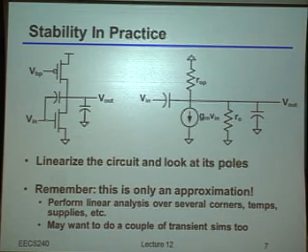Okay? In fact, it turns out there are even some more subtle, tricky things that you may want to check. So let's say your supply voltage was nominally 1.2 volts, and let's say from a static standpoint it varied by, I don't know, plus or minus 100 millivolts. Okay?